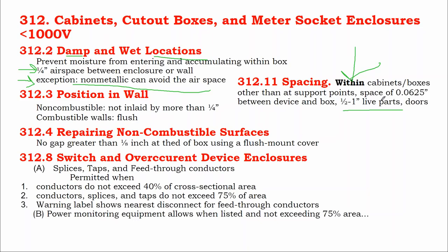If you're looking at your electrical box and it's made of metal, and then you're looking at those terminals that are energized hovering a couple of inches off the box, like, well, if I touch those terminals to that metal, what'll happen? You'll cause a ground fault. So if you're building your own box, you can't get too close to the edge or the lid.